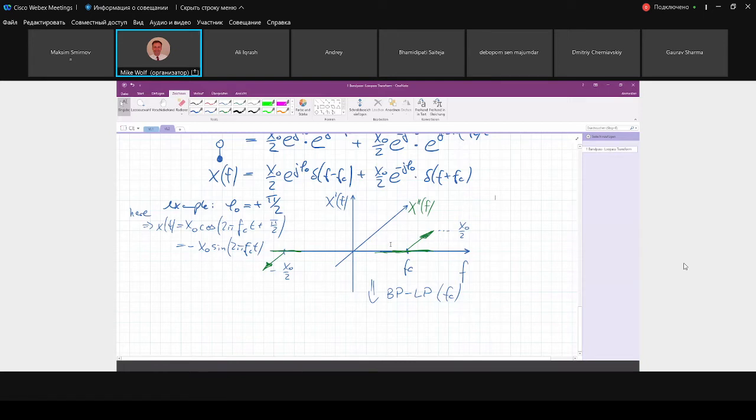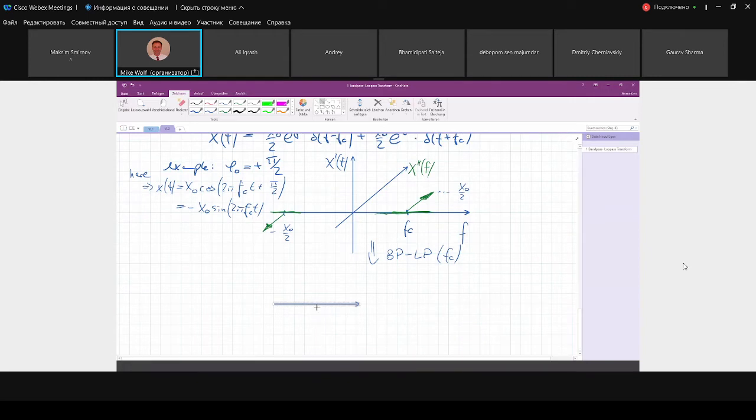So now we shift this with respect to the frequency fc, and what we get is, of course, very simple, and we end up in this figure. In this case, it's really so simple that we don't need a figure. We can just work with equations. Here's f. Here again, let's say this is X prime of f, but in the equivalent low-pass range, this is important. Low-pass range, this shift, and you see now this is exactly.